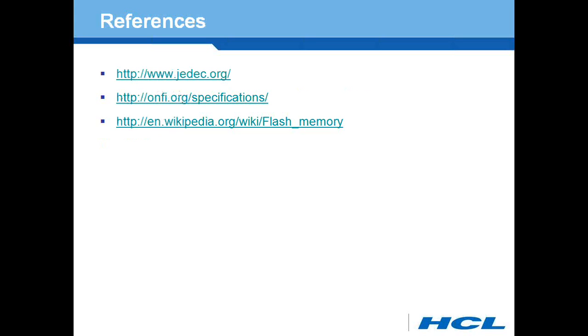Before we close this seminar, flash memories are suitable for applications where a large amount of data has to be stored. Because of some special characteristics, the system should be designed to take care of block management, error correction algorithm, and wear leveling to keep the data for a long time.